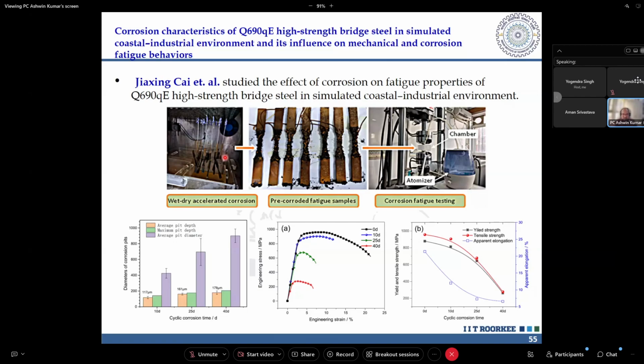Yes, it is true, but the correlation between real corrosion in the atmosphere and the accelerated corrosion which we are doing in some chamber or by immersing in some salt is not really equal. There are no relations right now to predict it. It may be true for one city, it might not be true for another city, what you are trying to do between atmospheric and accelerated corrosion.